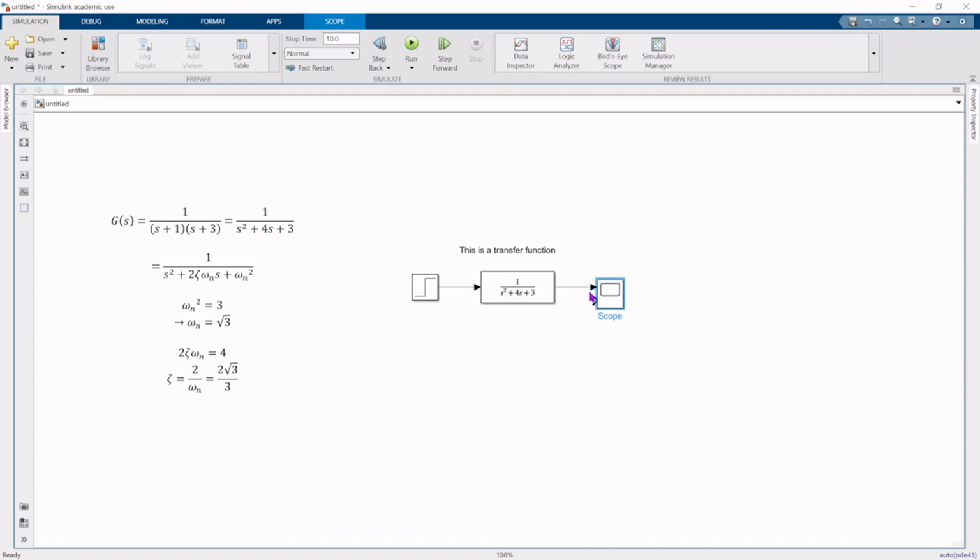The first input is still connected to the output of our transfer function, but we now have the second input that we can send a signal to. So we're going to connect that to our step input, just by dragging it to the signal line for the step signal.